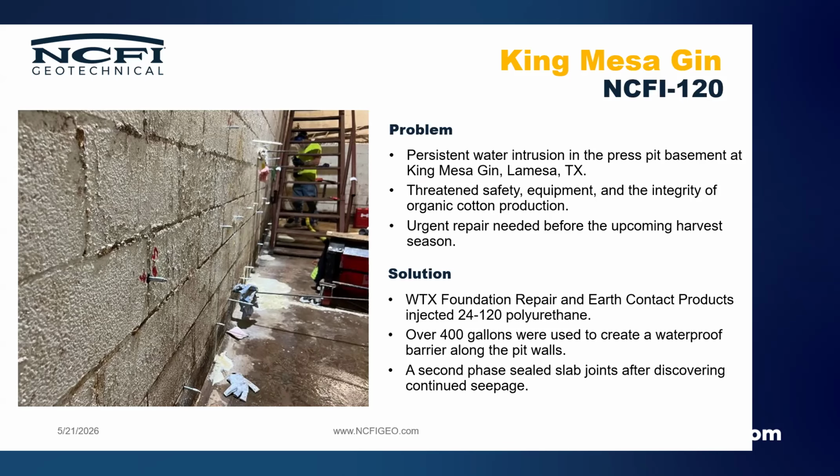CMU walls can be a little trickier. If they're not filled with concrete, you want to try and get to the dirt side. If they are filled, then you're good. If they're not, then you can end up wasting a lot of grout filling up the CMU. We've actually done some projects where we took one of our dual components that's designed to fill up CMU walls and use that to fill that void first before doing the curtain grouting. It works really well.